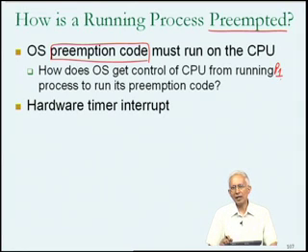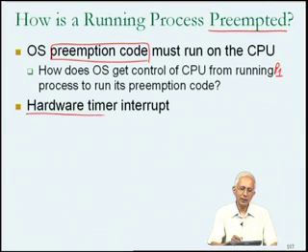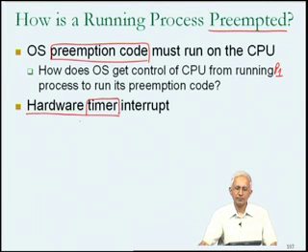And the form that the hardware support takes is a small piece of hardware called the hardware timer. And essentially, when you hear the word timer, you normally think of something which counts time, and that's basically what this piece of hardware is doing. It is something like a clock, which periodically will try to grab control of the CPU. And the way that it grabs control of the CPU is using a mechanism called an interrupt.